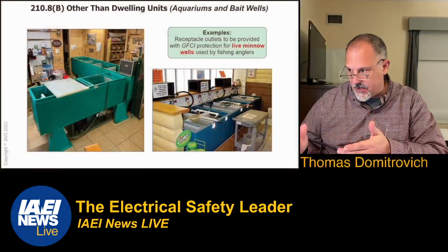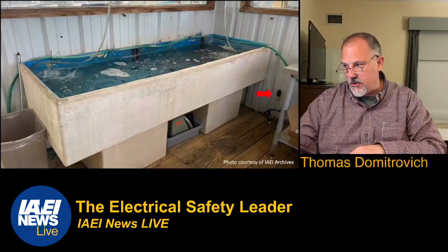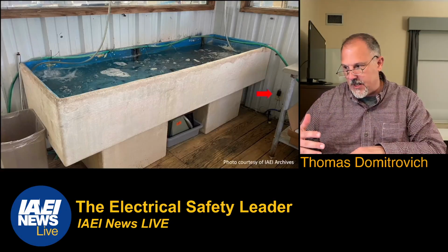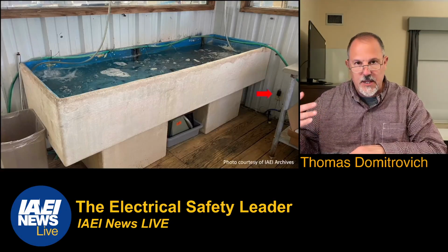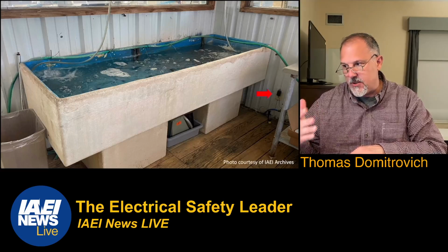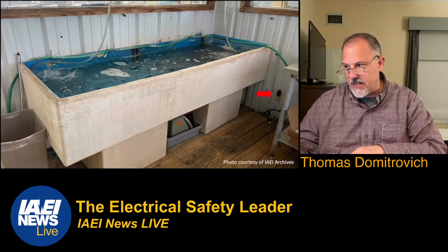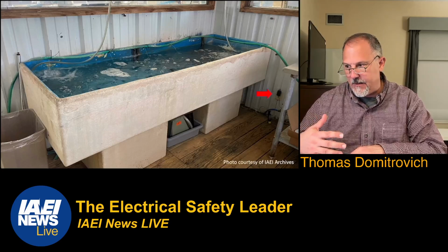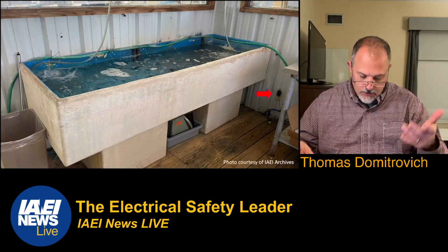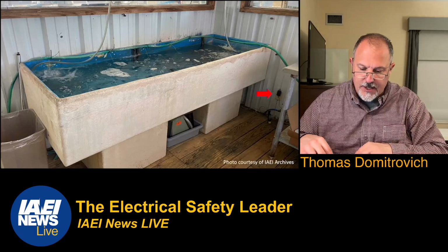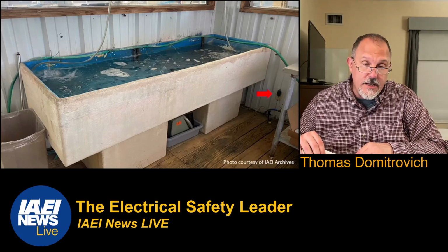These types of items are those fixed and stationary items. This is in your bait centers and things of that nature. There are receptacles very near to this. In some cases, they may have aerators going on like this does. You might have heaters. I don't know. All kinds of stuff going on in those applications. GFCI protected. It's not a sink.